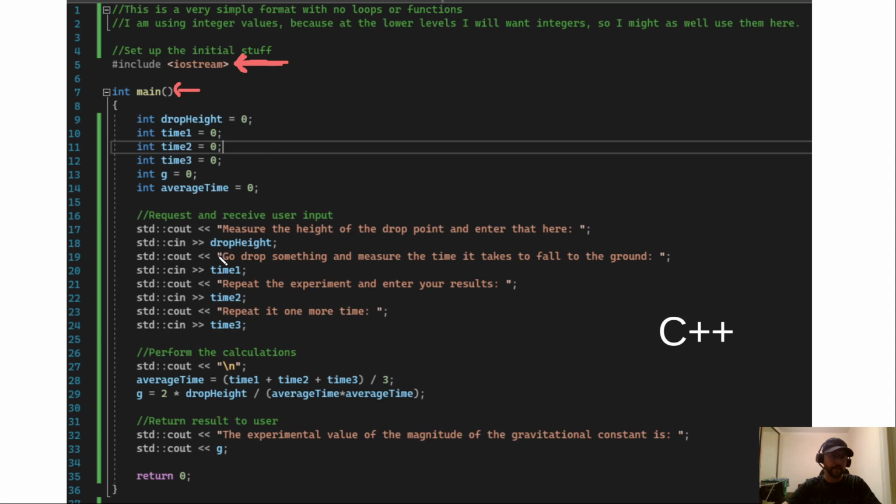And interestingly enough, later I'm going to talk about STL, which is used in Step 7 for Siemens PLCs. And there they use organizational block 1, is what they call it, but it's basically the exact same concept. The program logic starts there and ends there, and anywhere else it jumps, it jumps from there and then jumps back.